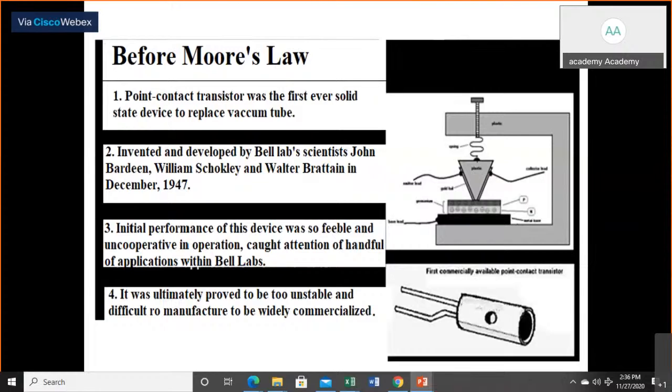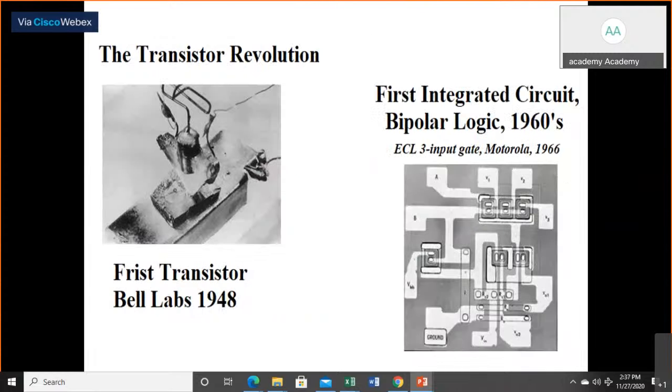But the problem is that the BJT is not bilateral in nature. It has an emitter and a collector that are not exchangeable, unlike the MOSFET, where source and drain can be exchanged very easily. That's why realizing integrated circuits is easier with MOS devices.